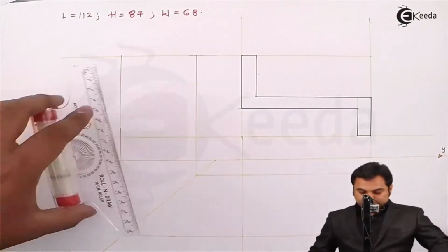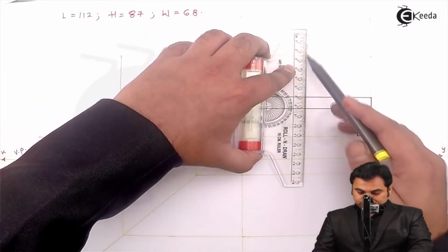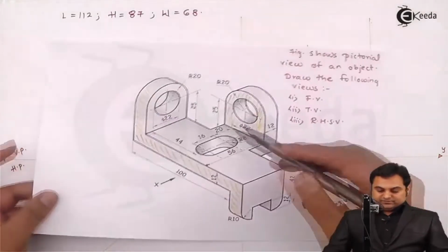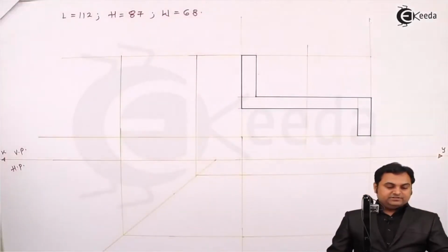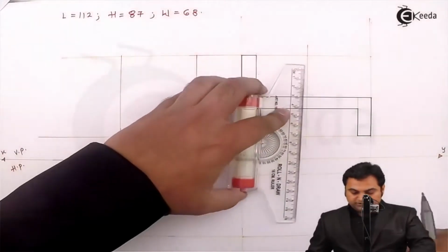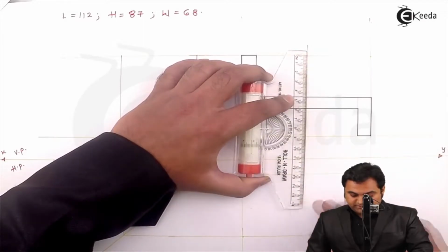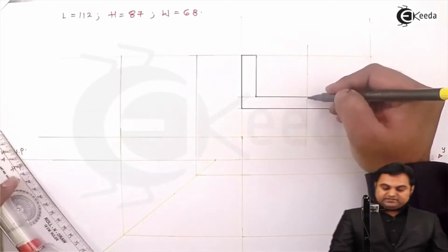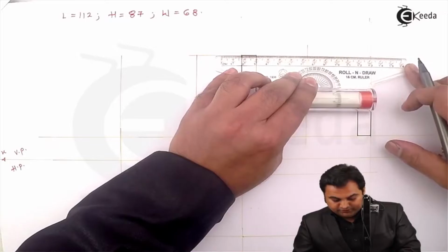projecting it light. This light line is the center line. And now I have to draw the semicircular plate. So after 25 mm height, here is the center. So over this, I am measuring 25 mm, or in other words, taking 20 mm from the top because the remaining height is 45, and then drawing a light horizontal line through it.